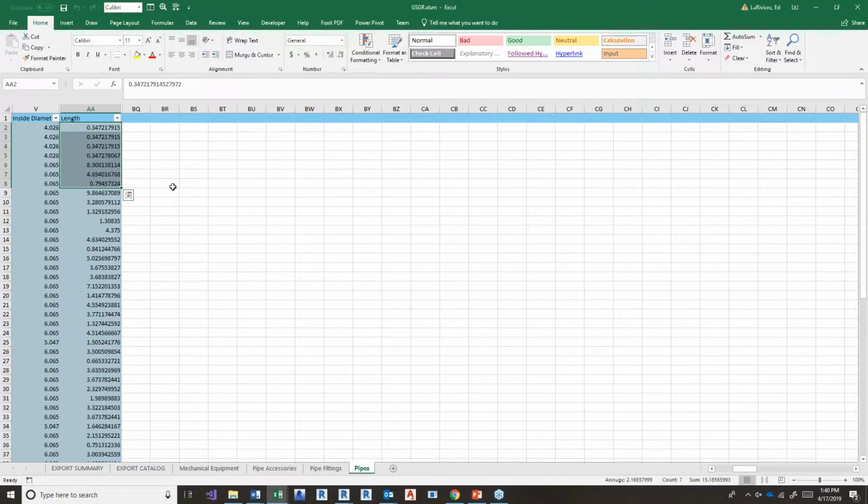So that makes sense if you understand Revit's drawing units, how pipe size is in inches, length is in feet. We'll have to pay attention to unit conversion if we're going to do the math. So let's say the length. Let's calculate this then. I think it'll be easier in square inches, and then we can convert it later. So let's do length times 12 times the inside diameter, caret, squared, divided by 4.